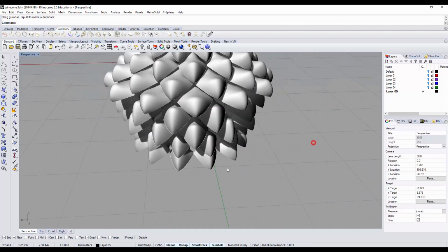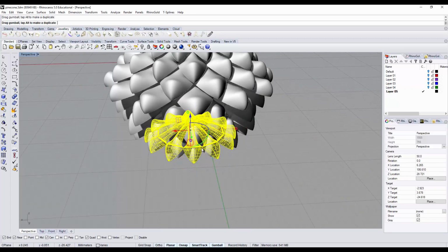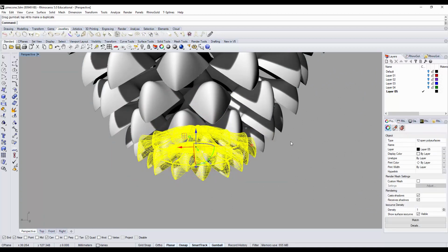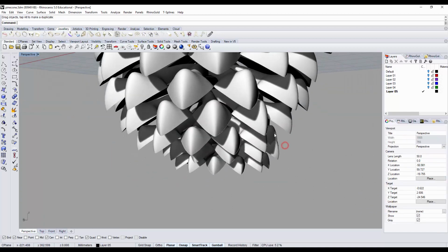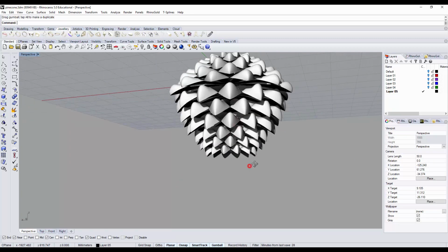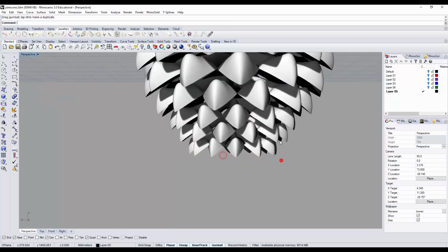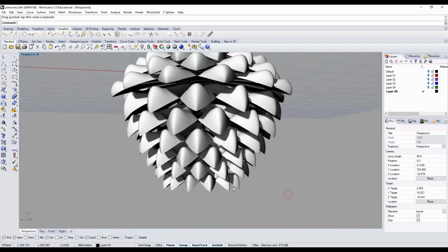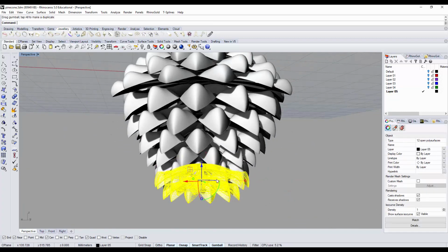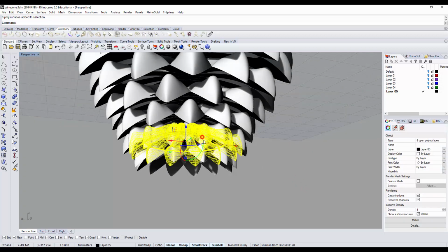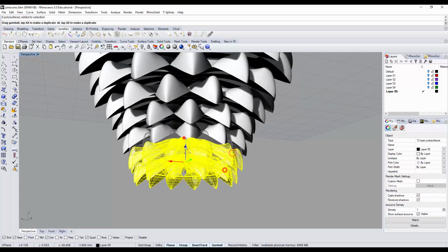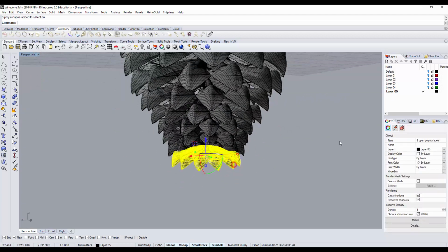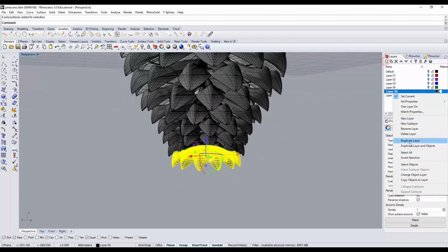If you need to make them thicker, what you can do is use the gumball and then scale 1D, which is dragging one of the squares, and that way will help you to only go in 1D instead of 3D. Again, if you're holding the shift and drag any of the squares, then you are doing 3D scaling. So I'm about to finish here to the very last one.